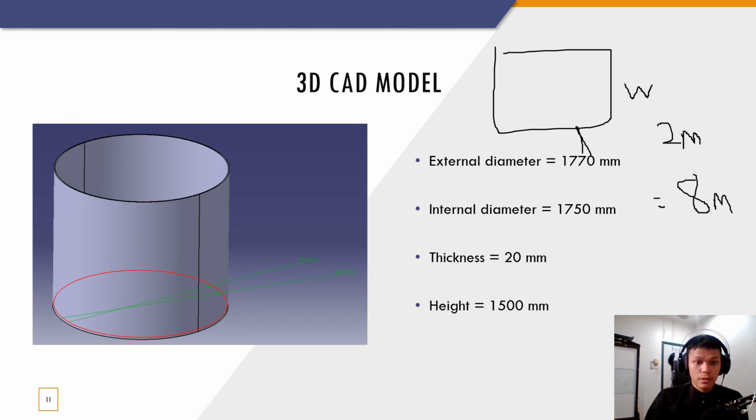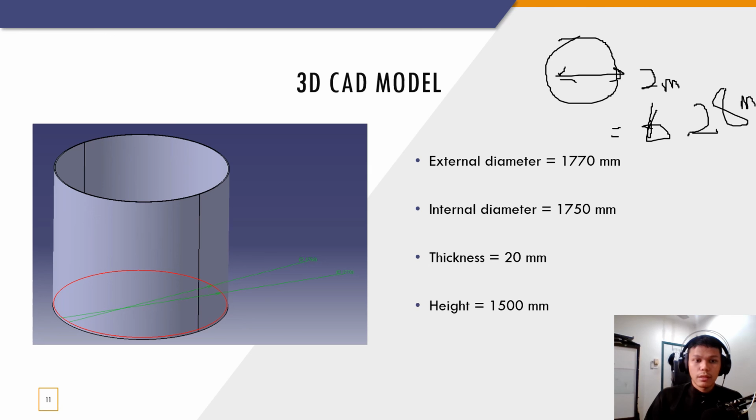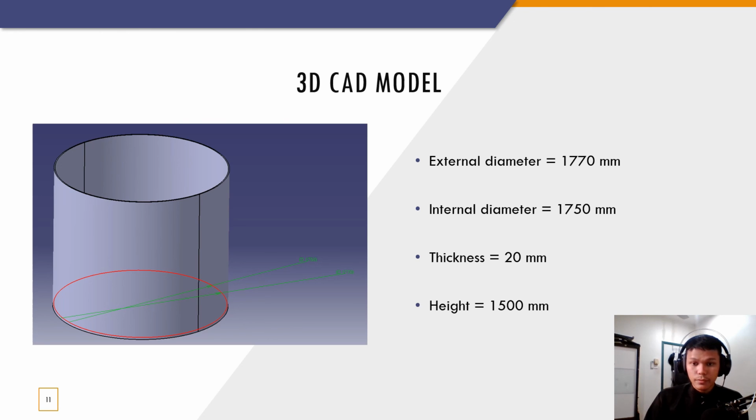In comparison, if we were to use a cylindrical tank having a diameter of 2 meters, the perimeter will be around 6.28 meters. That is significantly less surface area exposed compared to using a square wall. For the square wall, the surface area is larger, causing more fluid to be exposed and more heat loss through walls will occur.